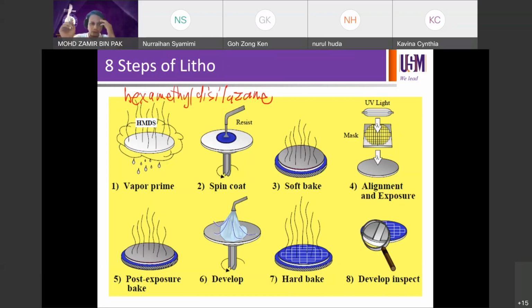So what you have to do is you have to vaporize HMDS. HMDS is a liquid, so we will vaporize it and then send the vapor into the track. I think that I discussed briefly on the track and scanner, but this one happens in the track, the first equipment. Then it's going to coat a very thin layer. Okay? So we're going to go through the process shortly. It normally takes place at around 90 degrees to 100 degrees C for 30 seconds, more or less, to coat the glue layer, or HMDS, right?